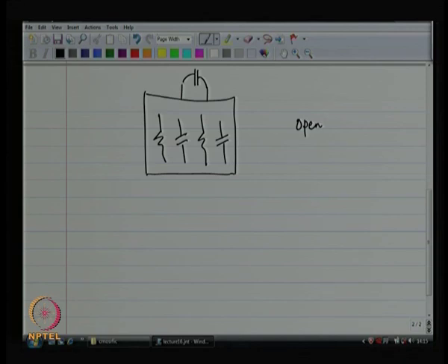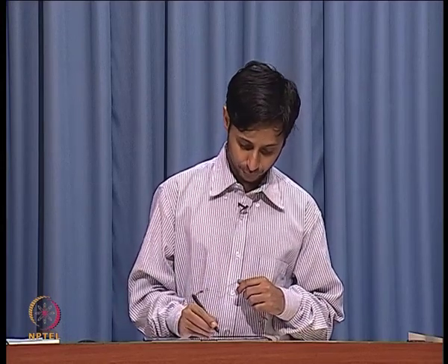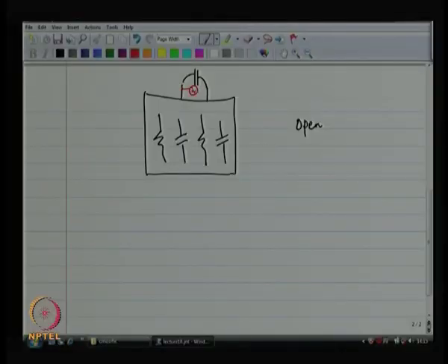Then you replace the capacitor that you have pulled out by a voltage source and find out the current that it draws. So, that voltage source divided by the current will give you the resistance. In other words, you do not have to do any of these replacements. What you need to do is find out the impedance looking into the network from these two terminals. What is the impedance that you see? Once you have that figured out, then R times C, that resistance times C, will give you the time constant corresponding to that particular open circuit time constant, right.